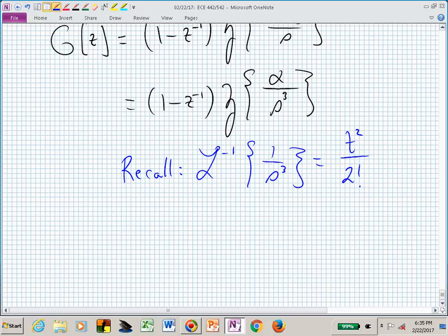We won't do it yet. We'll probably do it the next time, but we would want to sample this analog waveform. We now have 1/2 times t squared. But what is t? When we sample, we're replacing little t with little n capital T. So we now have little n capital T, that whole thing squared. So now we want to Z-transform n squared. T squared is just a number. We can factor that out. Is that clear?